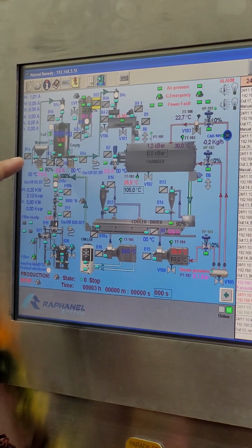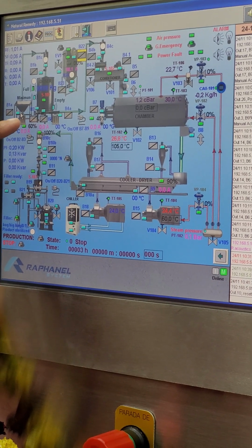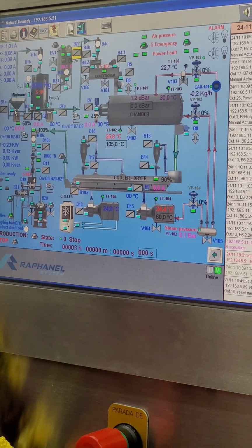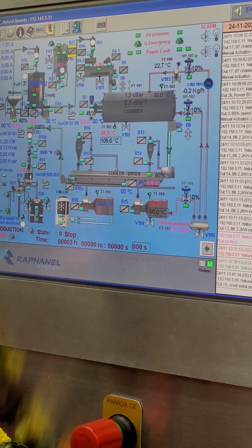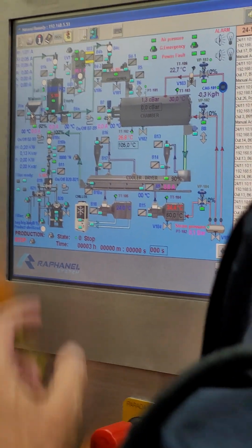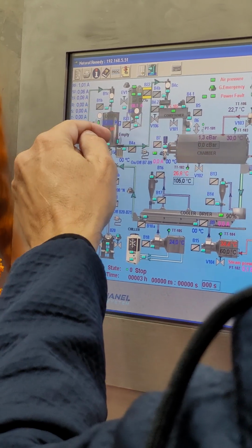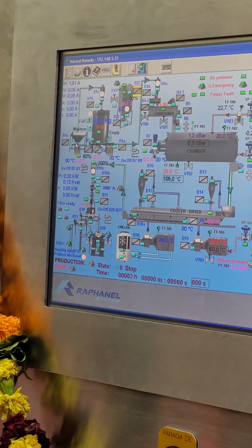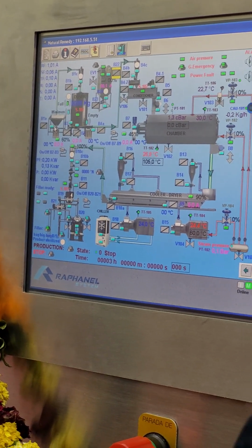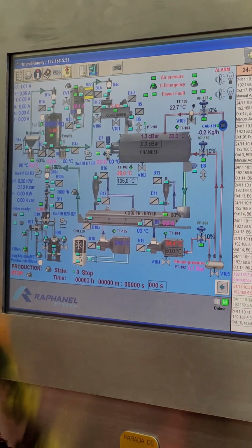Somewhere the material is jammed itself, in the hopper or this rotary or the pneumatic pipe. Somewhere it's not reaching. Nothing is overcurrent. There's no overcurrent anywhere. The plant continues running, no problem, but the material doesn't reach. The light is green. The doser, okay. If the doser doesn't have weight, then no work. It's controlled through the doser.